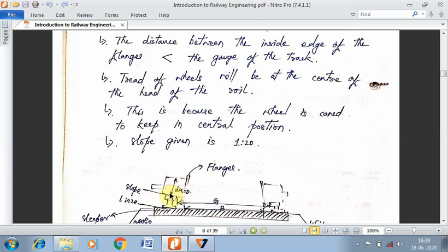Now to see to it that this is aligned, the rail also will be tilted to this particular slope of 1 in 20, and the platform on the sleeper, the top section of the sleeper, which holds the rail and that of the wheel, also will be with certain slope. If you happen to observe the sleepers, just pay close attention to the section that I am showing.